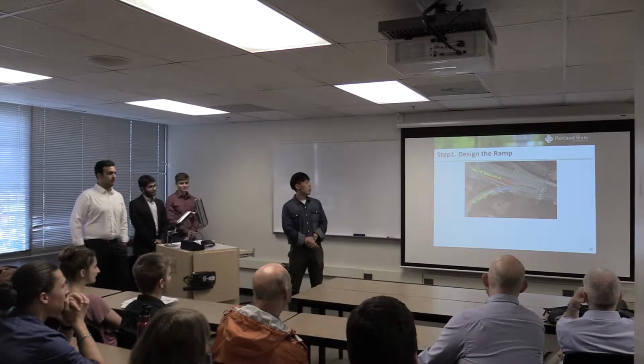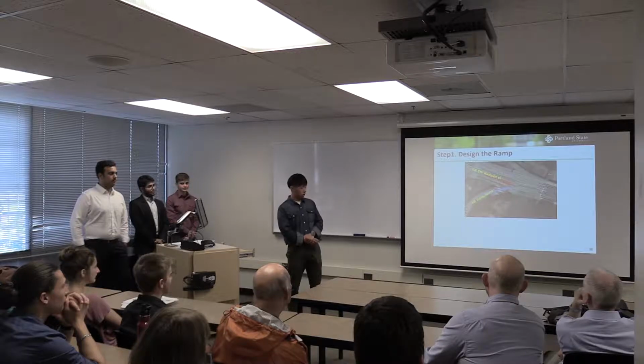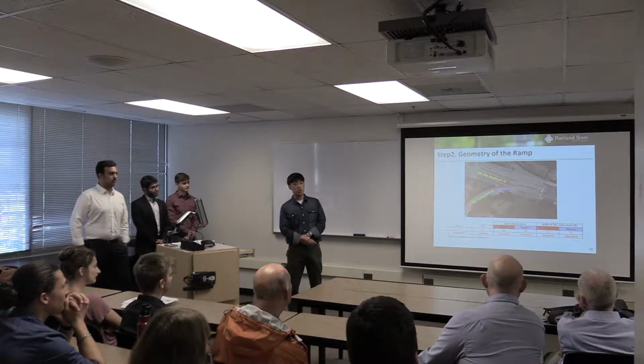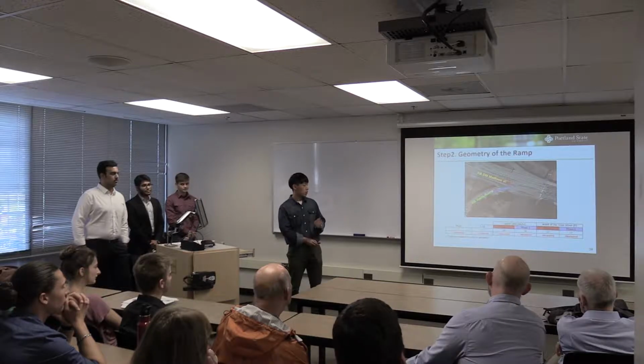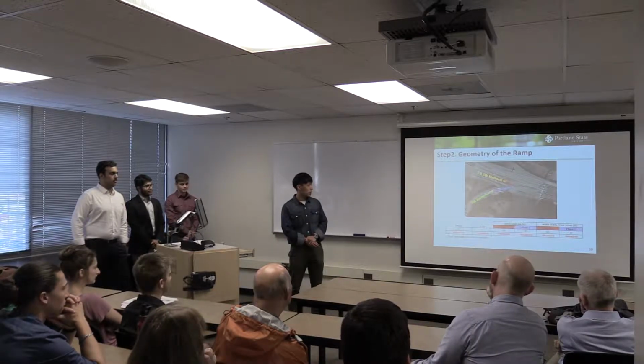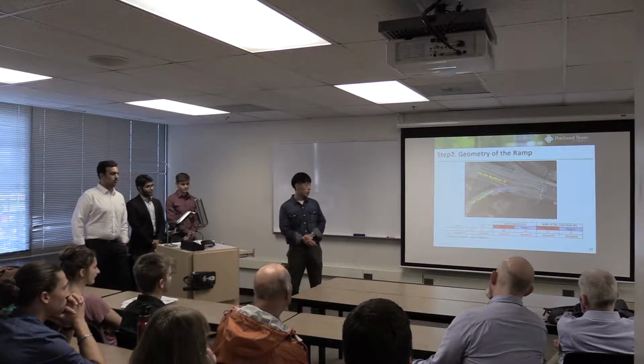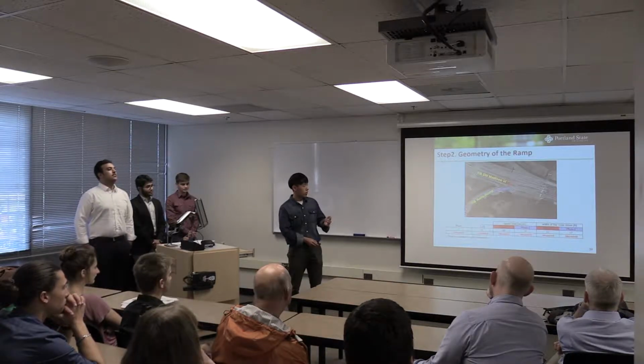So for the first step, we divide by 2 phases to calculate our signal timing. And then we input our geometry data. So since we have 2 phases, our total lost time was 8 seconds, 4 seconds for each phase. And we input our speed limit on the side and then width of the cross street.